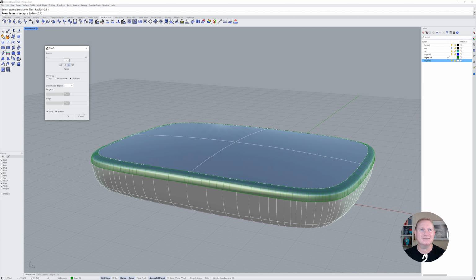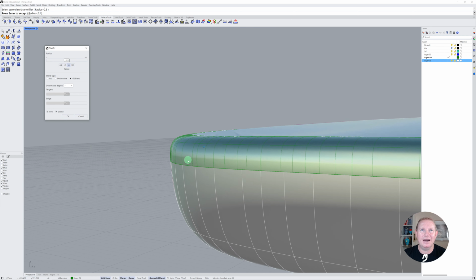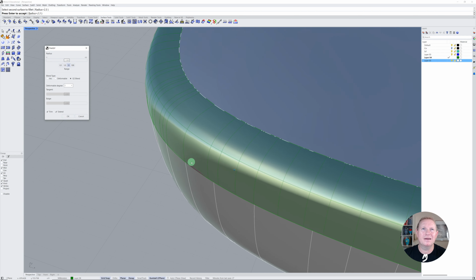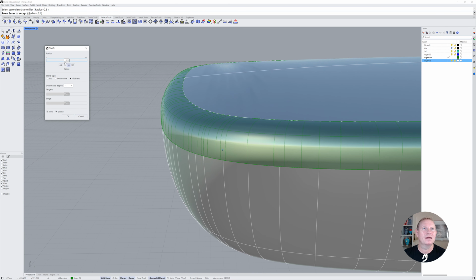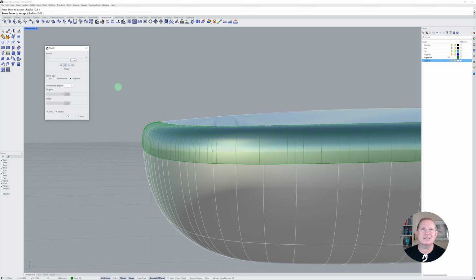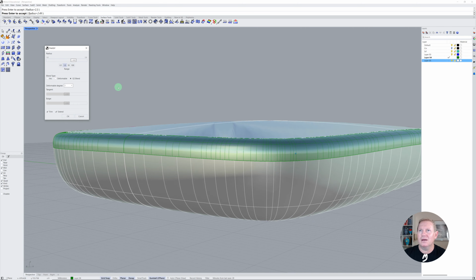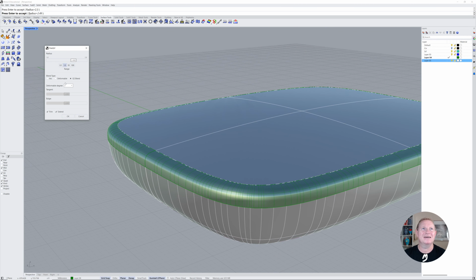We didn't look at this in class. This is actually acceptable blending, and we can see our highlight here, and we can actually see how our surface is flying. And we can explore a range in which we can look at deforming our radius. So at the moment it's about 2.3. We can adjust that. And we can actually see that we're getting a good transition on this surface as a G2.